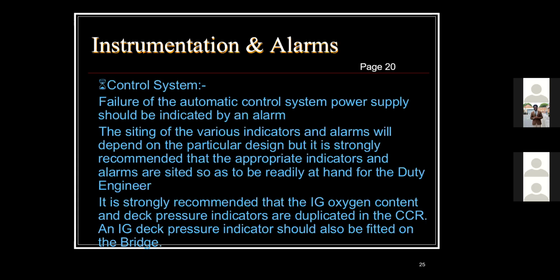Before you commence crude oil washing, COW, which you tend to do at the end of loading just to remove some of the sediment, and it's also a MARPOL requirement that a certain number of tanks should be crude oil washed every quarter, the IG, inert gas system, must be fully operational. All alarm systems must be, because that is the case where you tend to get a lot of explosions. A lot of things tend to go wrong during crude oil washing.